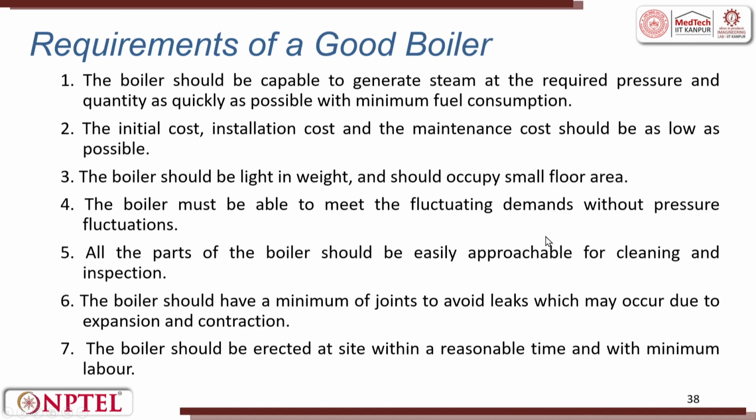What are the requirements for a good boiler? Because everything goes around a boiler here. The boiler should have the capacity to generate heat at the required pressure and quantity as quickly as possible. This is very important. The initial cost should be low, and installation cost should be low. The boiler should be light in weight and occupy lower floor space. The boiler should be able to meet fluctuating demand without pressure fluctuation.